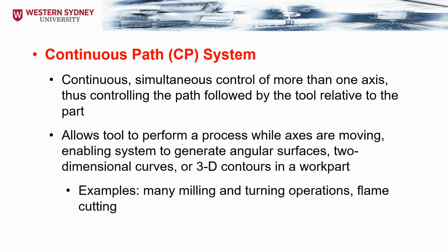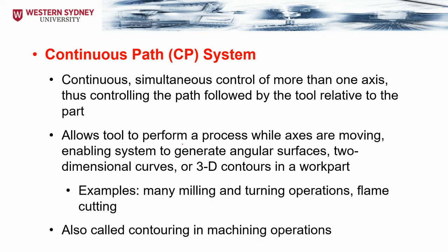It will allow the tool to perform the process while the axes are moving, enabling the system to generate angular surfaces, two-dimensional curves, or 3D contours in the work part. Examples of that are milling and turning operations or flame cutting. Sometimes we call it contouring in machining operations.